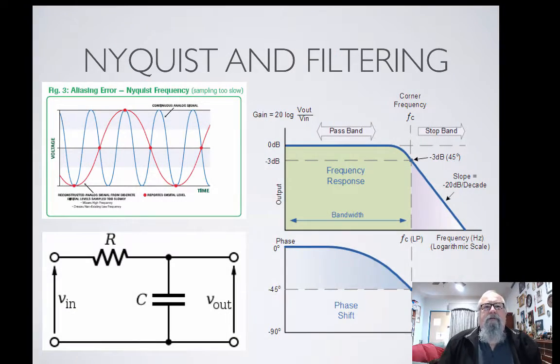Okay, so once we've decided on the signal that we're going to input, there's a few things that we need to consider. The first is a sampling rate. Sampling rate is in samples per second, and it must be at least twice the rate of the highest frequency component of our signal. So for example, if we want to read in a speech signal, speech has a frequency component up around 3600 Hertz. This means that our sampling rate must be at least twice that, or 7,200 samples per second.